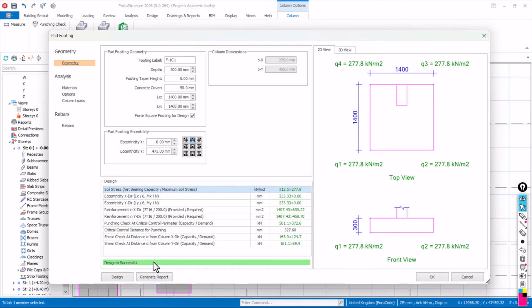All right, is this really practical? My answer is no. Don't forget that when we started, I always hammered on this: don't depend on what the software gives you. You have to give your own engineering judgment. We started that by checking our beams, and we saw that most times the software tends to increase the beam reinforcement size to 20 or 25. But later you can see that even 16 can be perfectly okay.